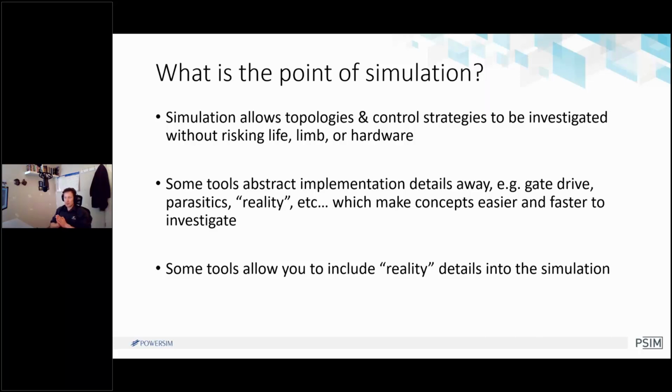If you're trying to build a 10,000 volt power converter, I probably want to simulate that first, because power devices exposed to that level of voltage, if they blow up, will vaporize things. Definitely don't want molten copper spraying on me. Also, those things, when they blow up, sound like a gunshot. So it could be pretty scary designing some of these things. Simulating it first, making sure that everything's going to be happy and not break, is an important thing.